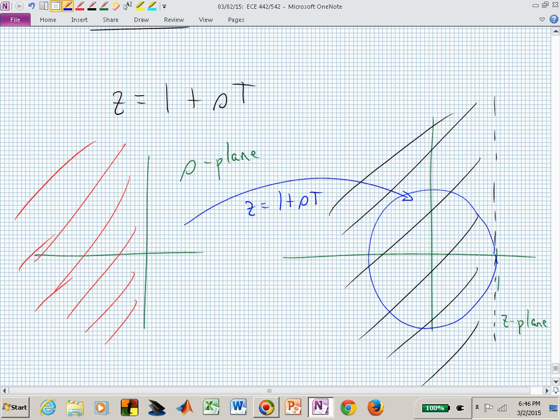The backward rule will, and so will the trapezoid. We're not going to have time to go into that, but the backward maps into a very small area within the unit circle. The trapezoid maps everything, the left half S-plane, right onto the entire unit circle. We'll pick up somewhere close to that on Wednesday.